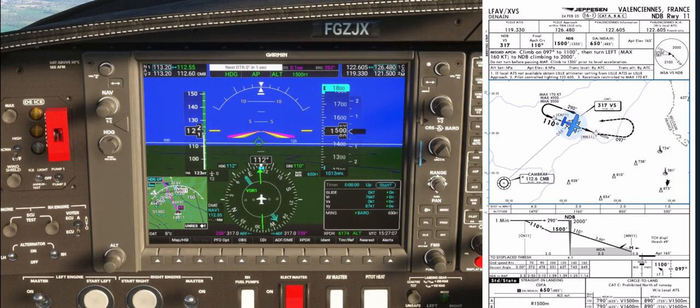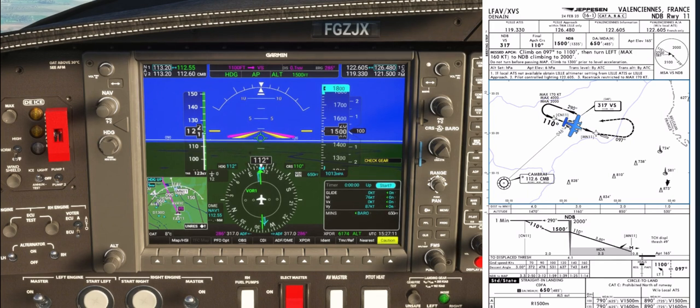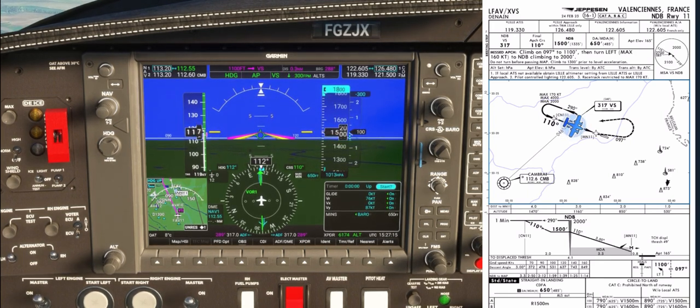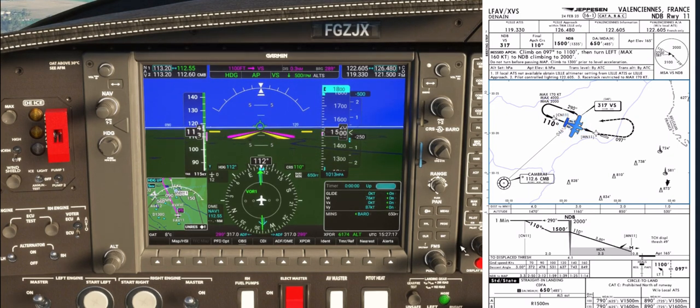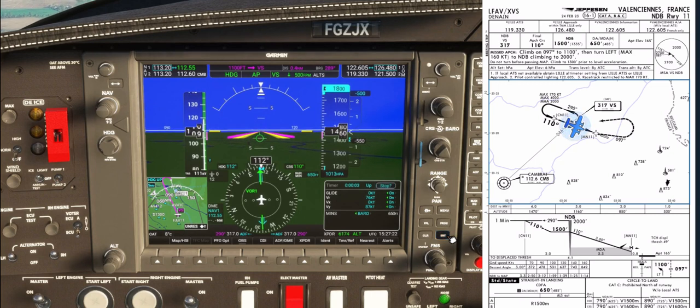At Victor Sierra. Gear, down. Glide, start descent at 600 feet per minute according to the descent scale. Go timer, start timer for 1 minute and 59 seconds. Go around altitude, set 2000 feet. Green lights, check gear and flaps lights.